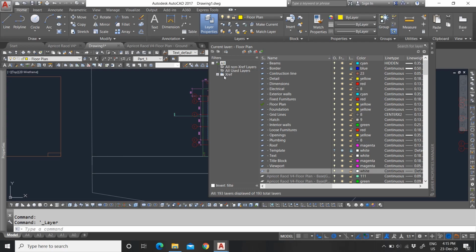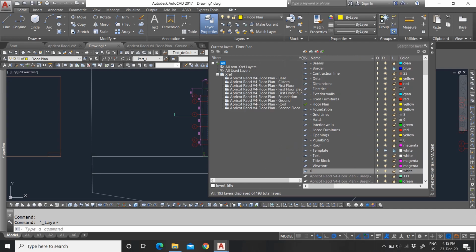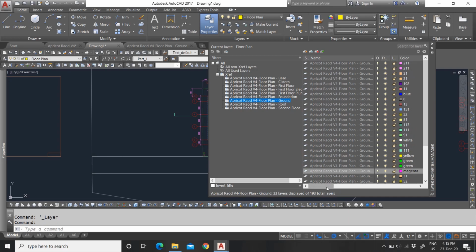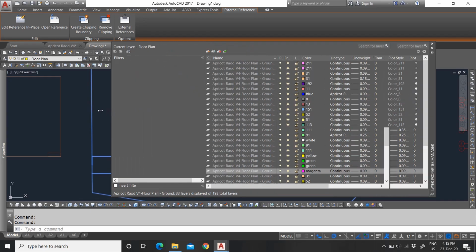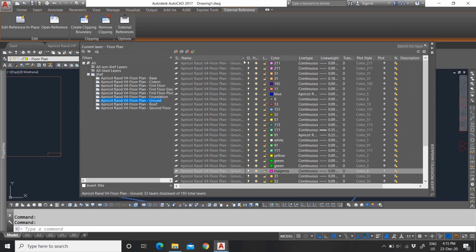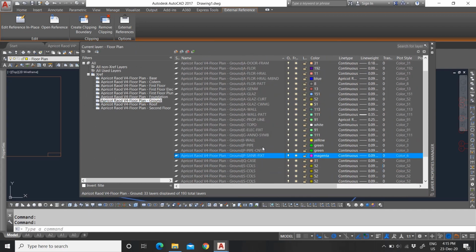So then if you go into your layer manager now, right on the Xref are all the imported drawings that we just imported. AutoCAD automatically does this for you. So by ground, the one we just mentioned here would have the layer called C topo. Let us see. Wait a minute. Let's make this a little bigger so that we can see. Okay, so C topo we can then take off.